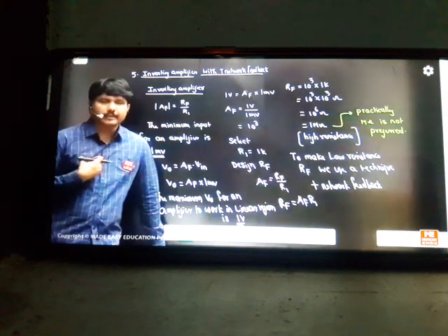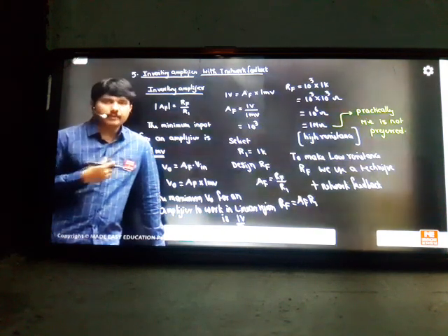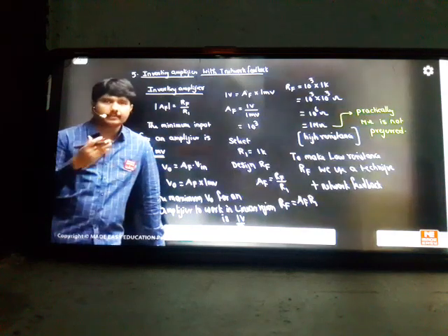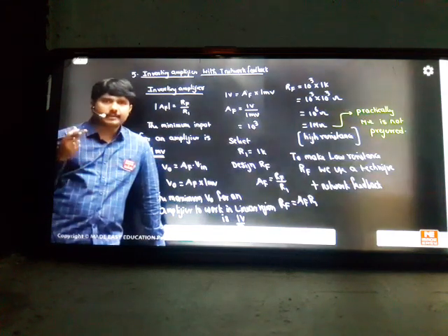So externally size is not a matter. That is the reason I have taken 3 resistors to analyze this topic. Not only 1T, you can make 2Ts, you can make 3Ts, like that you can design. Examiner can ask you with a 2T also. At that time you have to go for one more KCL and one more equation and you have to find out the answer for it.